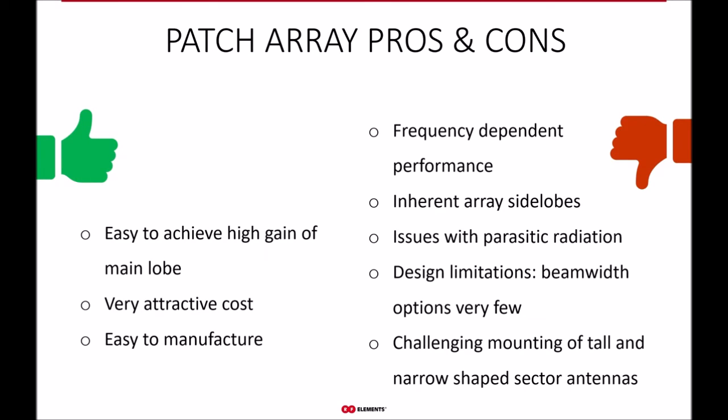So while patch arrays undeniably have the advantage of easily growing the gain and simple manufacturing, resulting in attractive pricing, from the point of view of what is needed in WISP networks, there are many cons. The present state of the industry is that the majority of WISPs claim their biggest issue is noise or interference. And this shows that the side lobes and other cons of the patch arrays are the issue that